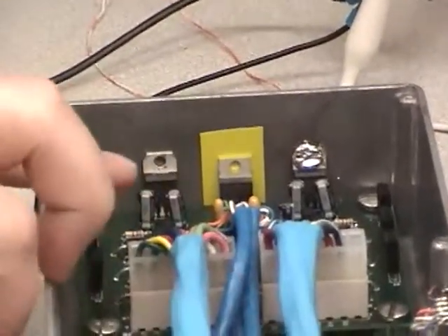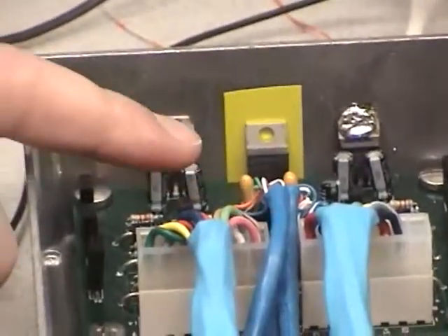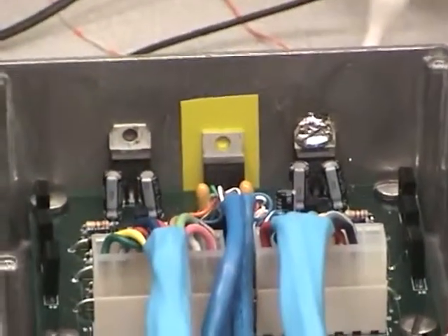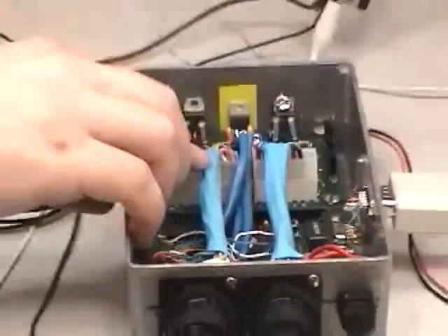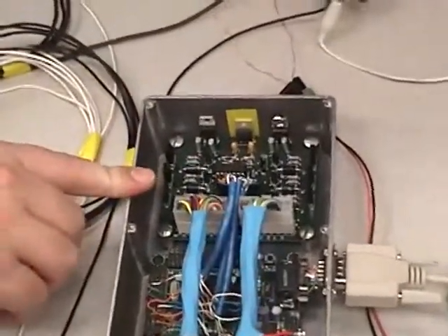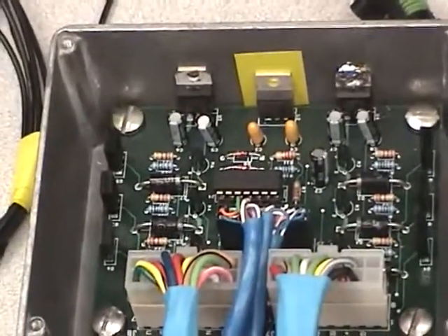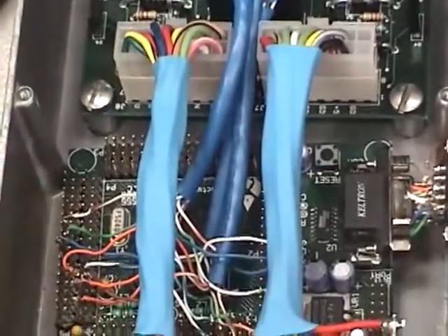So all this has to go through signal conditioning. We have a board right here that all inputs will go through and be filtered, like filtering sines or pulses into nice square waves for the microcontroller's TPU channels. And then all outputs are going to be triggering BJTs and MOSFETs to source the current from somewhere besides the microcontroller, because it obviously couldn't drive a 1 amp solenoid.